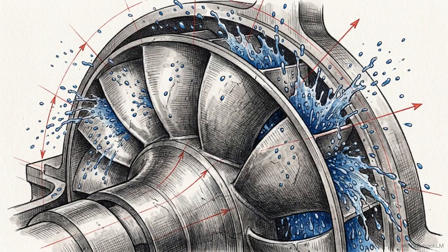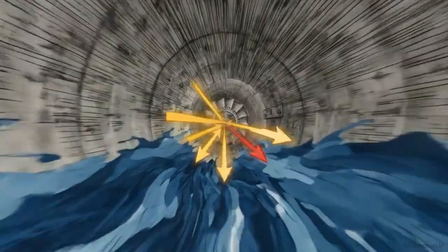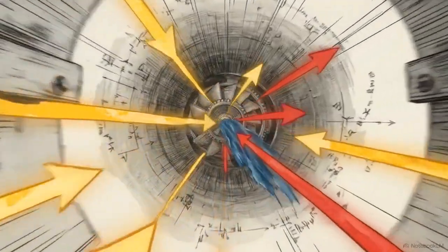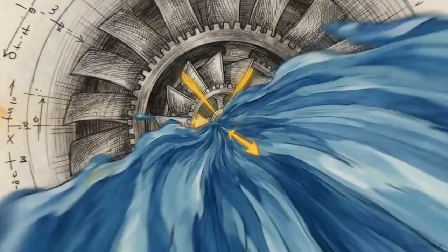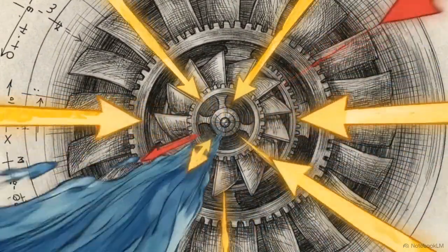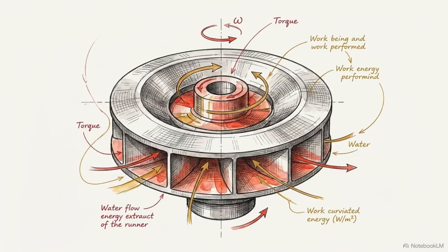The dam provides the necessary elevation and storage. The transition to rotational power is concentrated entirely within the turbine runner at the base. As water plunges down the interior of the penstock pipe, its pressure and velocity increase dramatically. Waiting at the bottom is the hydraulic turbine. This is the exact mechanical device responsible for extracting hydraulic energy from the fluid and converting it into rotational shaft